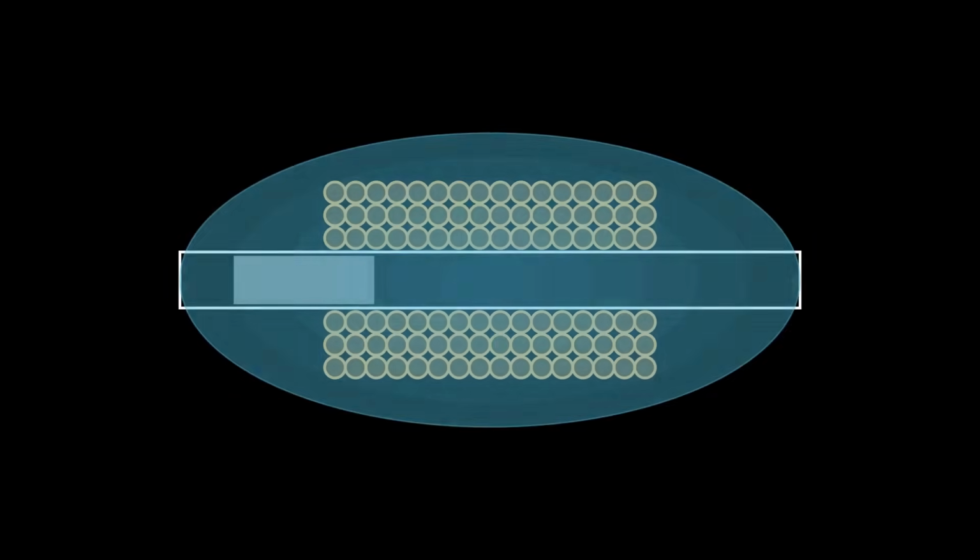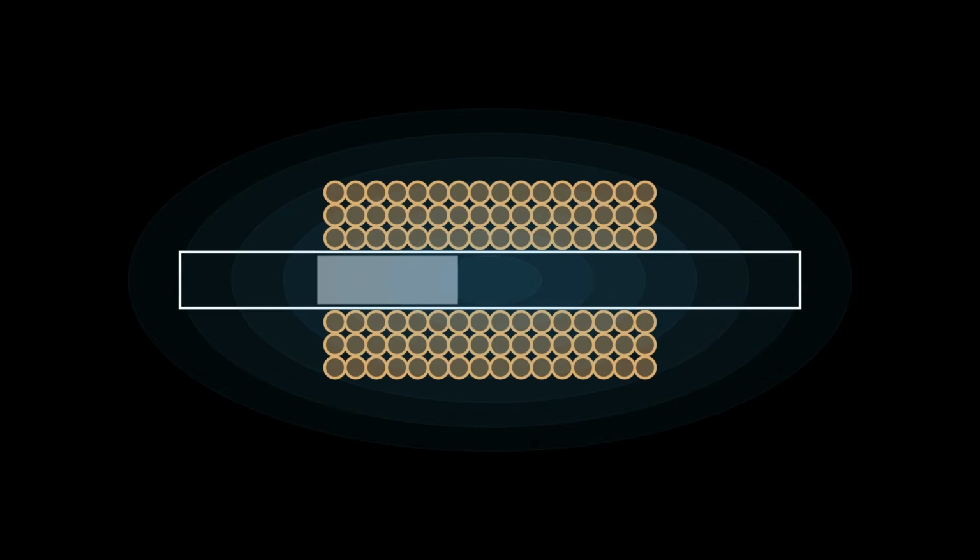This is due to the same magnetic force that accelerated the projectile at the start will now, if there is still current flowing in the coil, begin to slow it down as it passes the center and exits through the other side. The distance the projectile is placed from the center can affect its final velocity, as if it's placed too close to the center, the projectile won't have time to accelerate to a maximum velocity before the center is reached and the power is switched off.